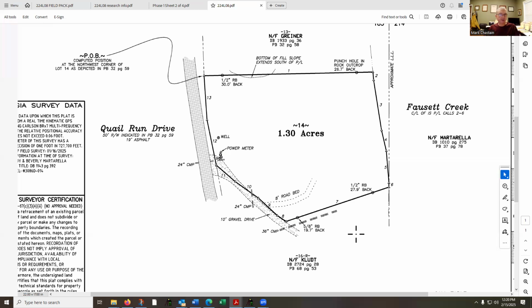You build the plat in, make sure it closes. If it doesn't close, then you know that your data from that is suspect. And of course, if it doesn't close the first time, try it again to make sure that you haven't fat-fingered a call.